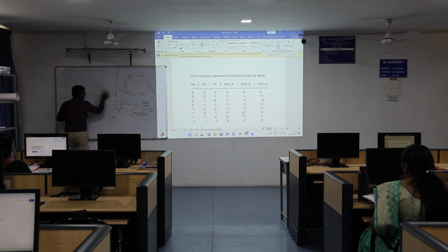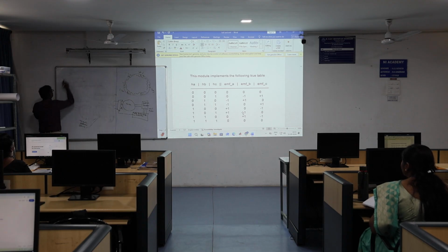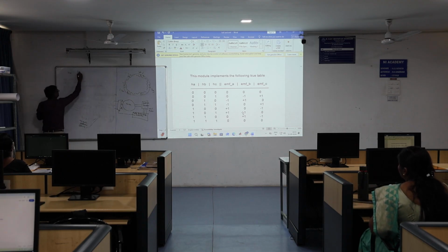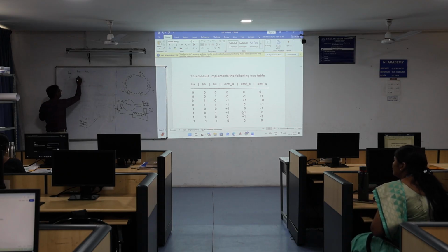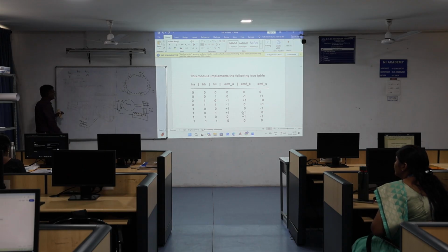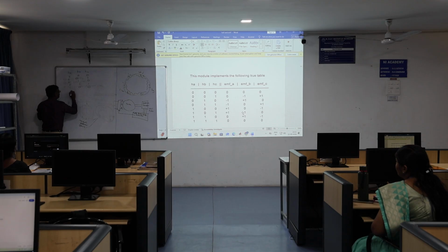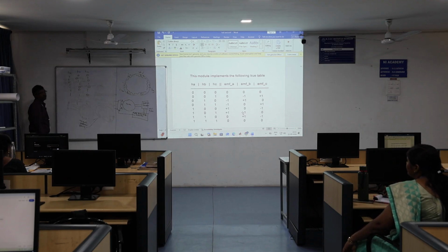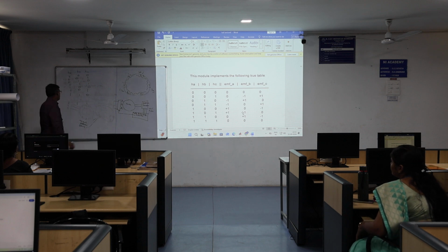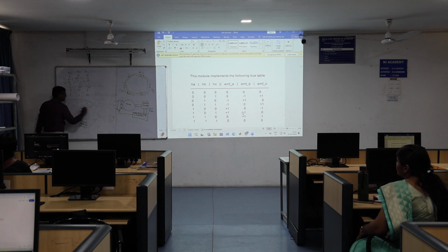So you have 3 Hall sensors, HA, HB, HC, that will produce 0, 0, 0 up to 1, 1, 1. So you have 0, 0, 1; 0, 1, 0; 0, 1, 1; 1, 0, 0; 1, 0, 1; 1, 1, 0. And 2 states are impossible in nature.